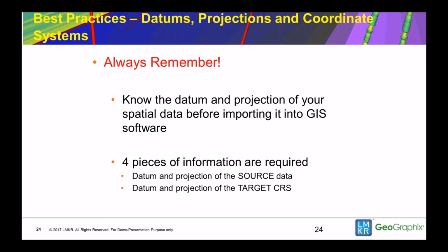One other thing I'll mention, that in Geographics you can shift your datum. So if you're bringing in, for instance, WMS or Web Map Services, and that Web Map service is in WGS 84, which most are, and you need to shift it into, for instance, NAD 27, fairly easy to do that.